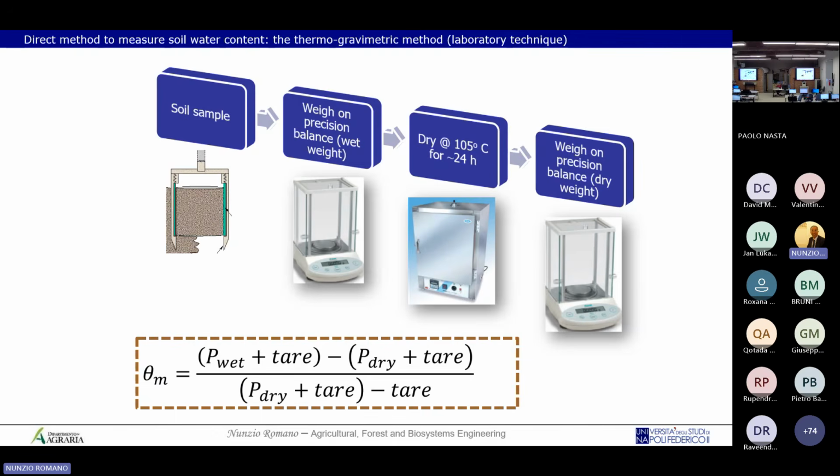Well, it depends on the thickness of the PVC. From my experience, if you have a PVC cylinder and the thickness is not too small, then you can leave it in the oven for 24 or 30 hours. But of course, you can check before collecting the undisturbed soil core. You can put your PVC cylinders in your oven to see if there is some deformation.